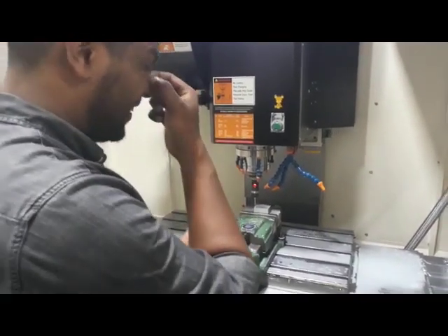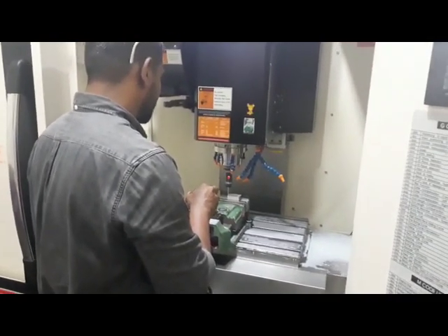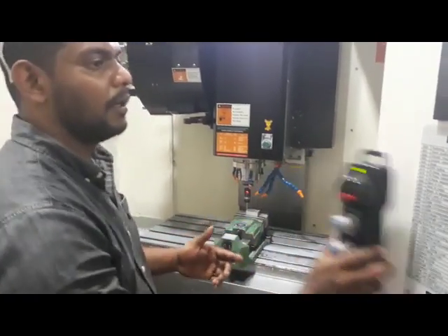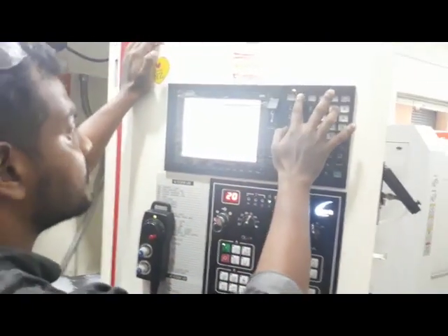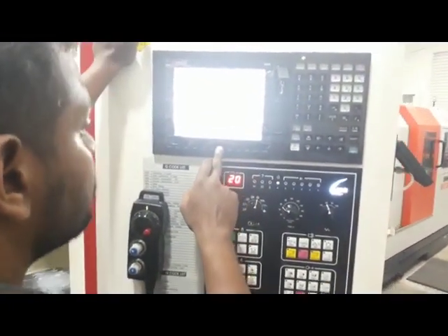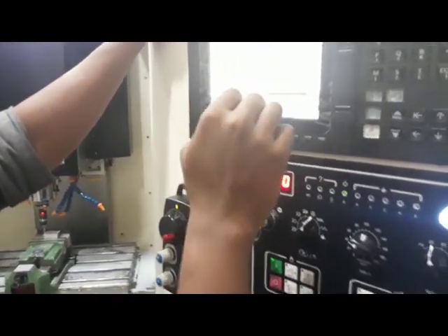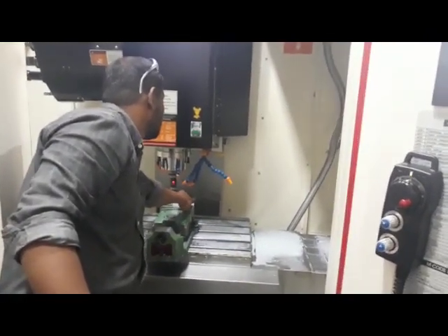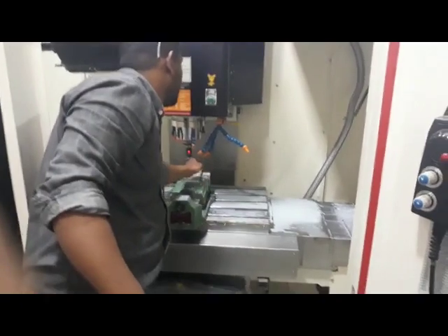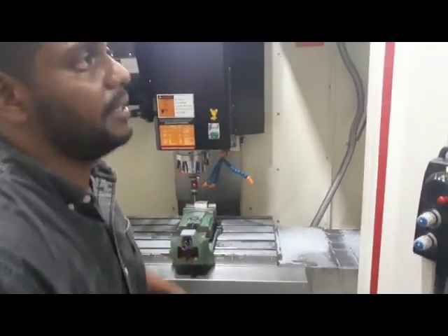So the moment I see the red light, I'm going to capture this position and explain to the machine where I am on the x-axis. The way I do it is I click on setup and then work measure. Then I click on the width measure. I need to measure both sides of the part, this point as well as this point, so it will give me the mean for x. Then I'll click on this point and this point on the y-axis, so I'll get the mean of x and y.